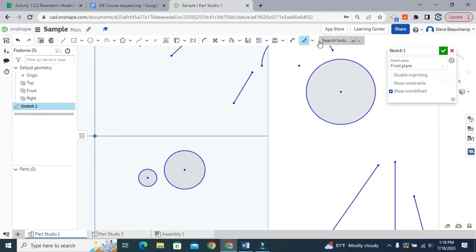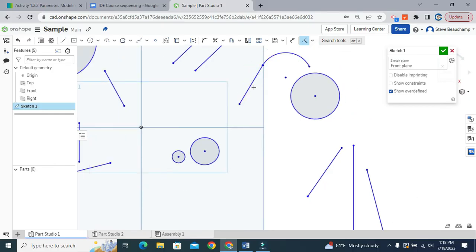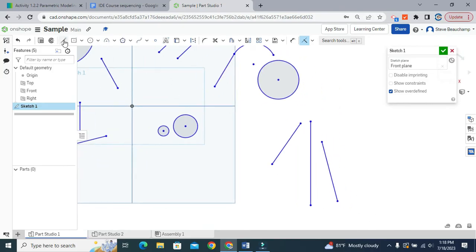Okay, and it did do that, but I'm going to place a coincident and make those two the same. And now you can see it goes straight from this line right into the curve, and this is a tangent surface there, which is good. The other one looks like I must have deleted my line there.